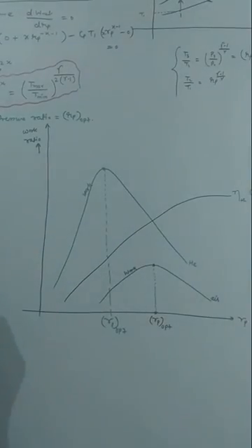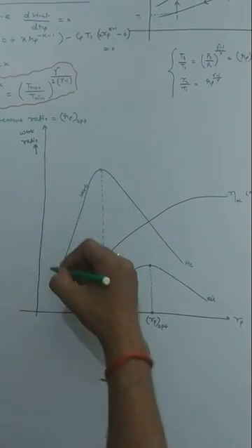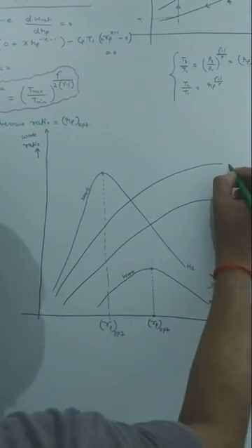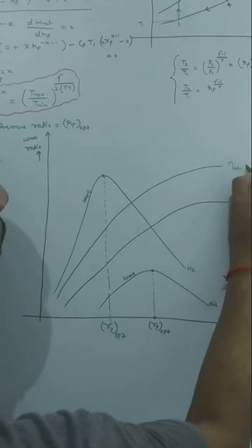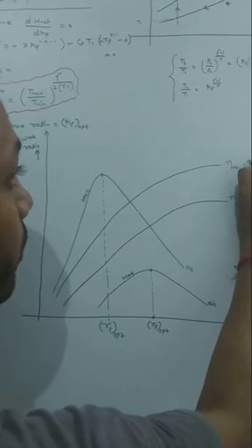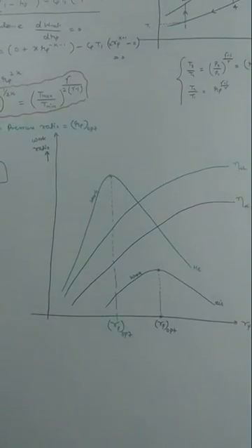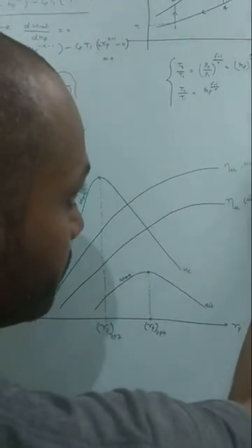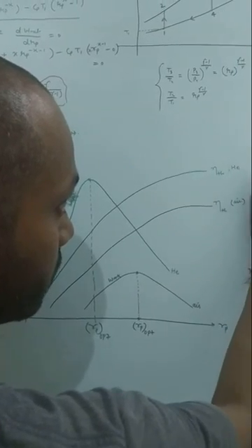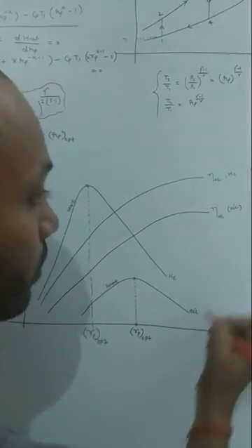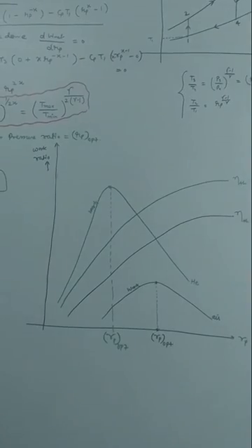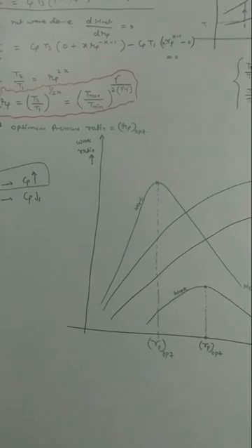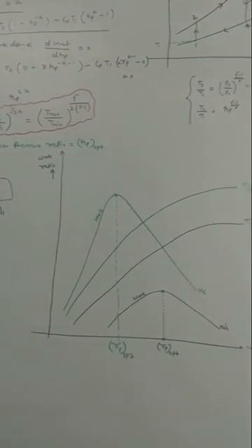And if you draw the curve for helium, then you will get the thermal efficiency of the Brayton cycle when you are using helium as a working substance. Then you can also observe that the thermal efficiency of the Brayton cycle or gas turbine cycles increases as you use a more efficient working substance like helium, argon gases.